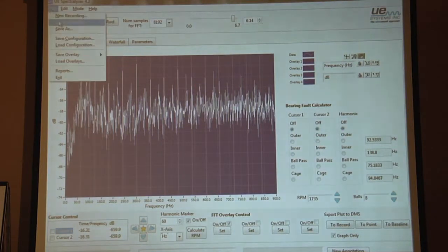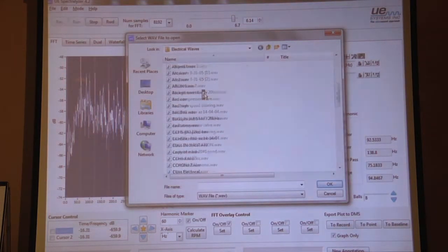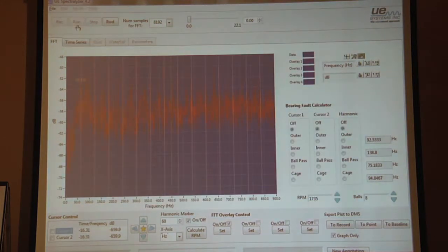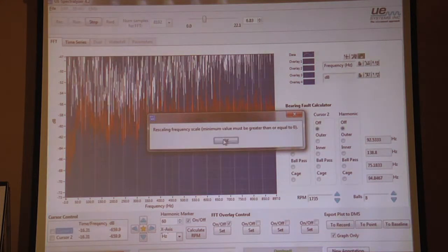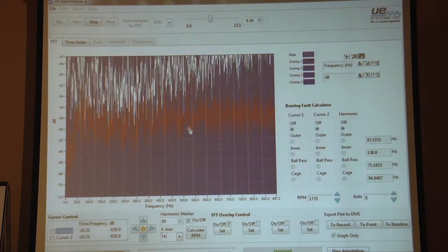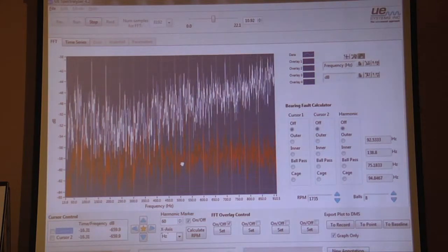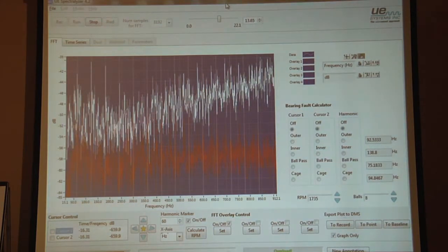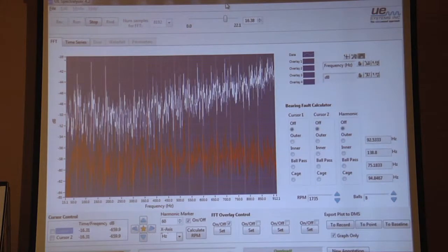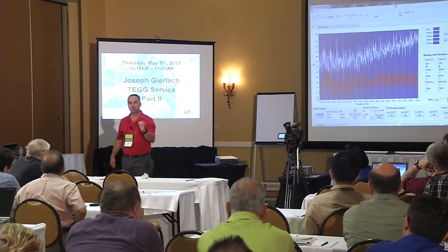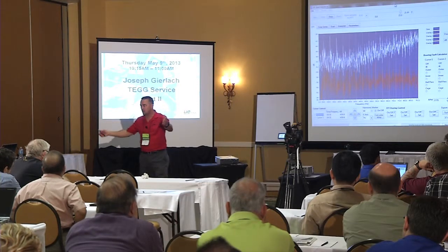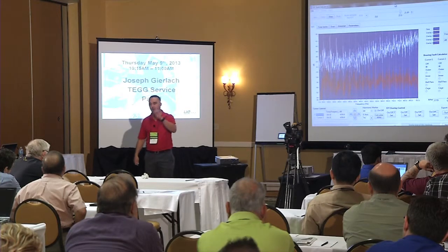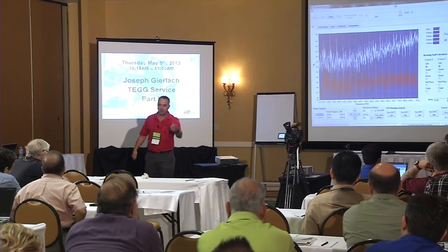So I think I have one here that is destructive. Does that sound tonally different? You hear that popping? What did we say popping is associated with? Discharges. So now, I think this is a 4160 volt transformer. There's going to be corona, but you got them pops. That's a key giveaway. What does that look like to you and I?